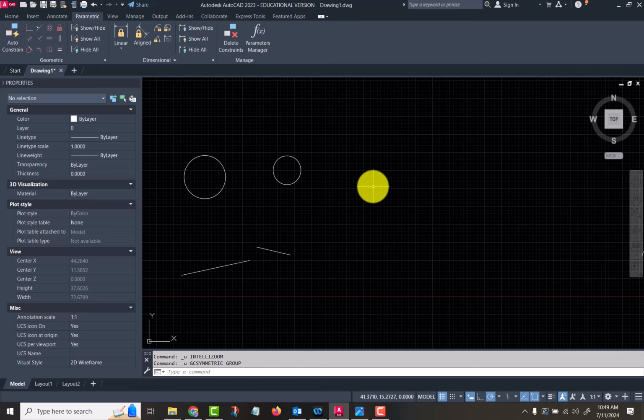If you work with Inventor, which is our 3D parametric modeling program on the mechanical side, you draw a rough sketch and then you apply dimensions and constraints, geometric constraints, to get it to be the right shape and the right size. It's a different thought process that you have to do.